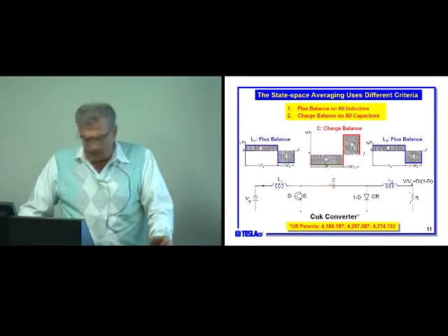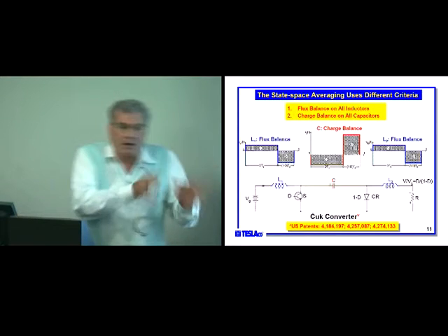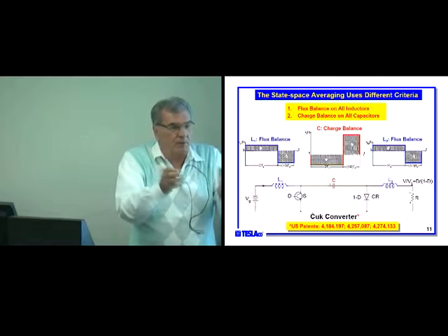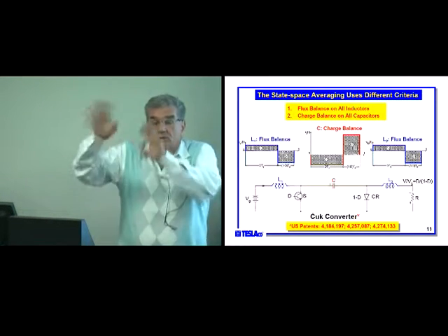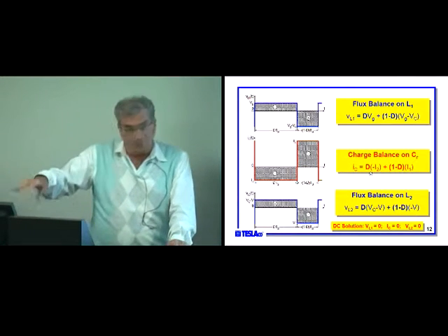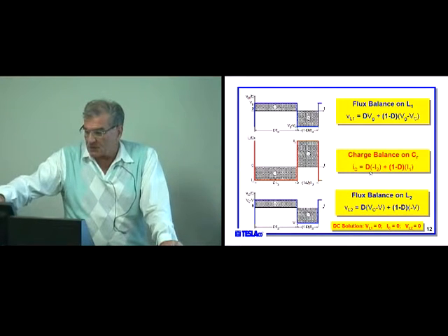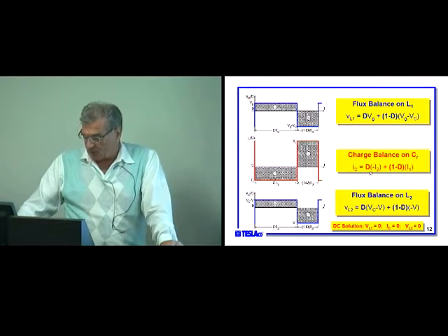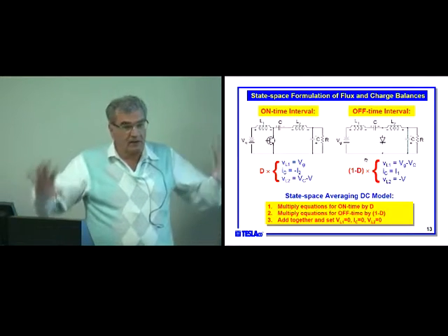But I went further, because our original contractor, NASA, TRW, gave us a goal. There is a buck boost and a flyback, so we want to model each one of them, and it's very simple, and you have a computer program, and then you get this whole thing modeled, and you can use it in the future. But it turns out, once you make these charge balance and flux balance equations, you see very easily that you can find this charge balance, volt-second balance, in such a way that for each position of the switch, on time or off time, you have 2 linear circuits.